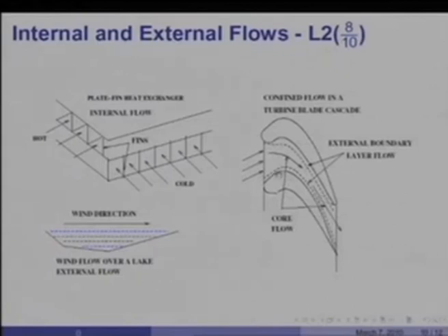The top surface of a blade is called the suction surface, the bottom surface is called the pressure surface, and therefore, this blade disc would move in that direction. You will notice that the regions where temperature gradients exist are very, very small compared to the total distance between the suction side and the pressure side.